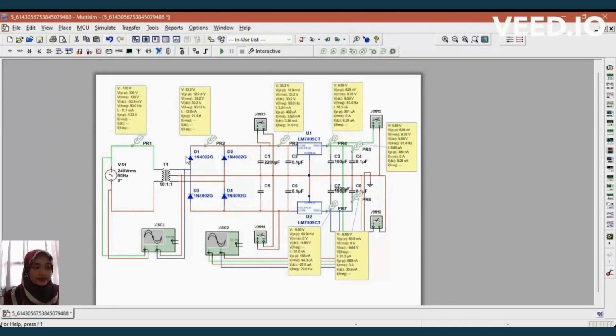Then this is a diode. The diode is a semiconductor device with two terminals designed to allow the electric current to flow in one direction while hindering the flow in the opposite direction. So its function is in rectification, converting alternating current AC, by facilitating the current to pass during the positive half cycle and the negative half cycle.